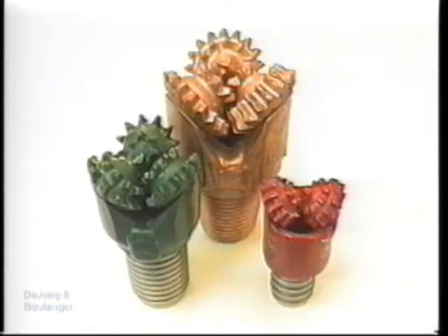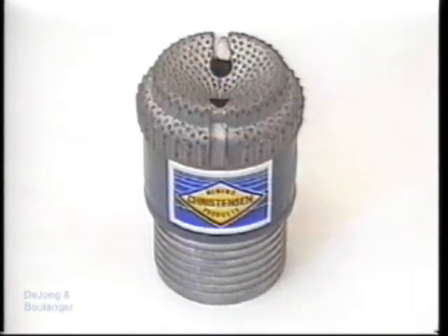The cone bit has teeth on the surfaces of cones, which rotate as the bit is turned. The spacing and size of the teeth on the cone depend on the type of material to be drilled. Plug bits come in three basic types: concave, pilot, and tapered. The concave plug bit, pictured here, is designed for drilling through relatively soft rock.